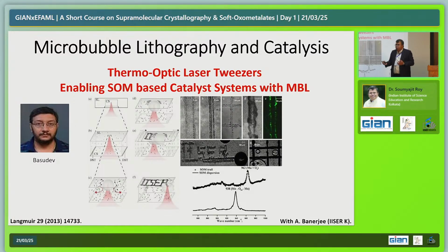which you are familiar with. So this is of course not nano, because with light, again, Kari showed in the morning the entire electromagnetic spectrum, and you know that with light here we cannot go to nano. We can stay up to a few hundred nanometers. Why? Because visible light has that limit. So you go to the limit of visible light with which you can do these types of patterns. So you can have patterns with widths of a few hundred nanometers.